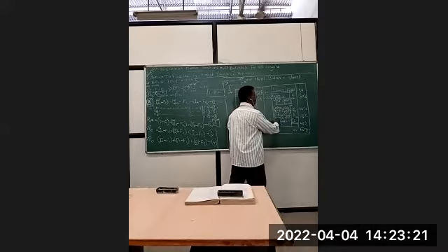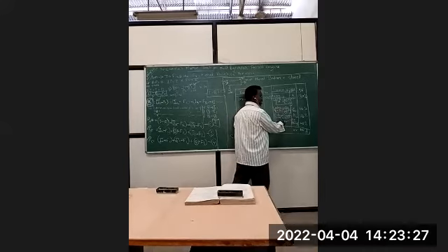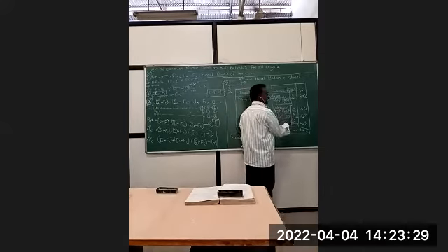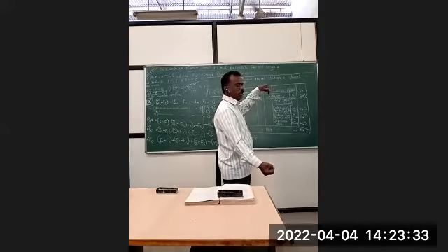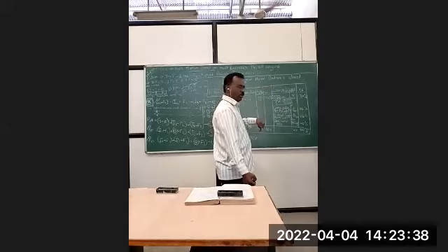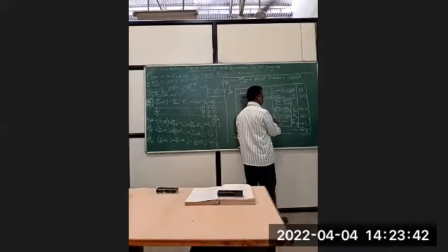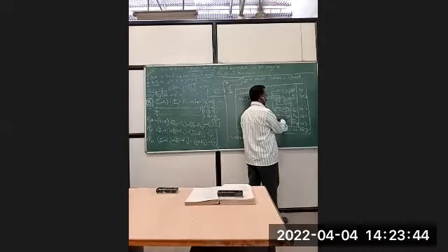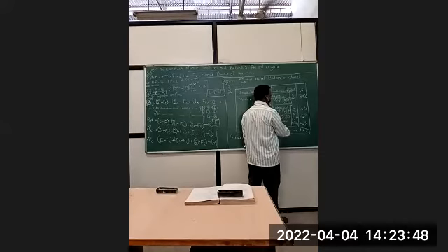So now Q is equal to mCp delta T, where m is the mass flow rate of the water flowing through the calorimeter, Cp is the specific heat, and delta T is the temperature difference between the temperature of water inlet to the calorimeter and water outlet from the calorimeter. Knowing these two temperatures and the mass flow rate, you can find out the heat lost in the exhaust gases.